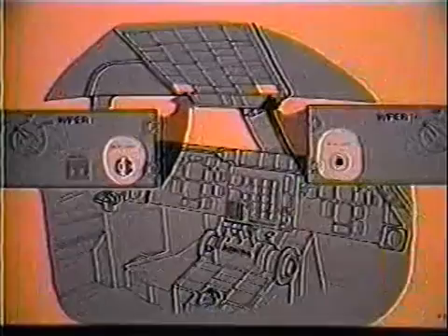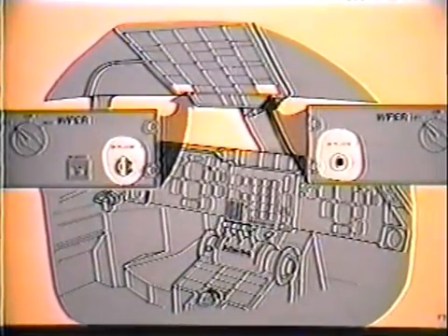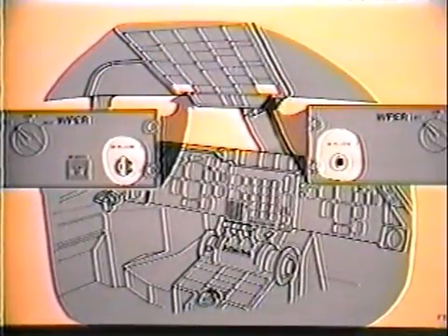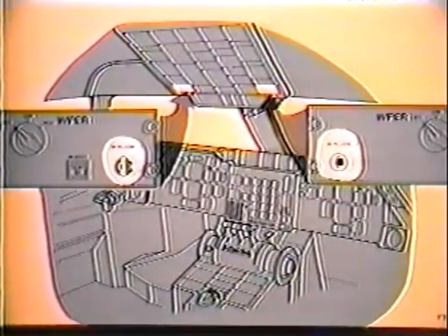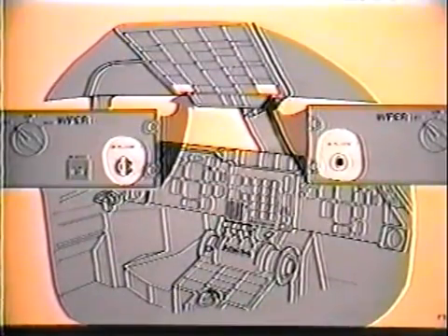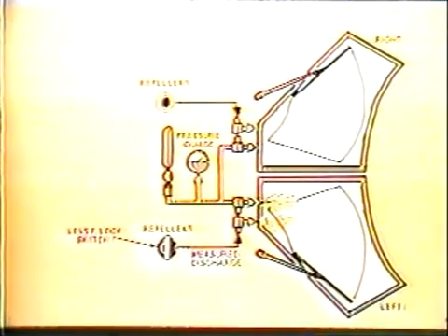Rain repellent. The rain repellent switches are on the windshield wiper control panels. Pressure for the rain repellent system comes from a pressurized can located at the aft end of the captain's side console. Actuation of the repellent switch ejects a measured amount of fluid onto that windshield. If more fluid is desired, press the repellent switch again. Holding the repellent switch will not create a continuous flow of fluid.